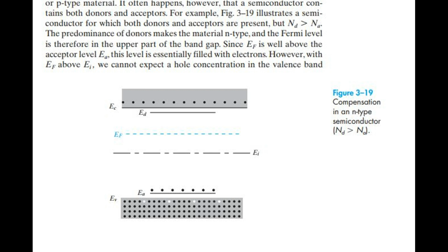By this process it is possible to begin with an N-type semiconductor and add acceptors until the number of acceptors equals the number of donors and no donated electrons remain in the conduction band. In such compensated material, n0 = ni = p0 and intrinsic conduction is obtained. With further acceptor doping, the semiconductor becomes P-type with a hole concentration of essentially acceptors minus donors.